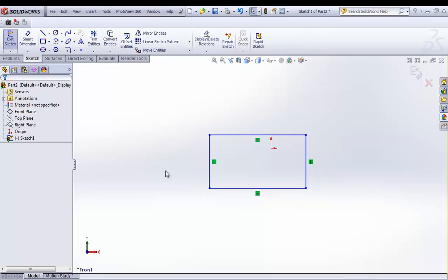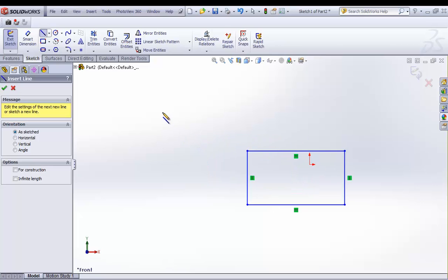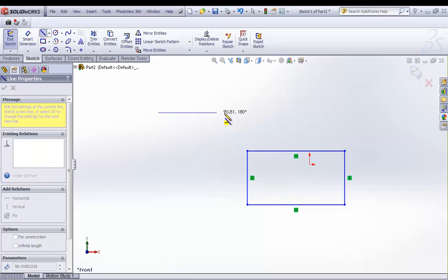Let's see if we can select the line tool from here. Now I have a few options. I can click for the start point of the line. If I move my cursor over here somewhere, my cursor changes to that angle symbol, which gives me 135 degrees. So if I carry on going in this direction, I know that I'm drawing that line at 135 degrees at that magnitude. If I go over here somewhere, it gives me a somewhat similar effect, 45 degrees.